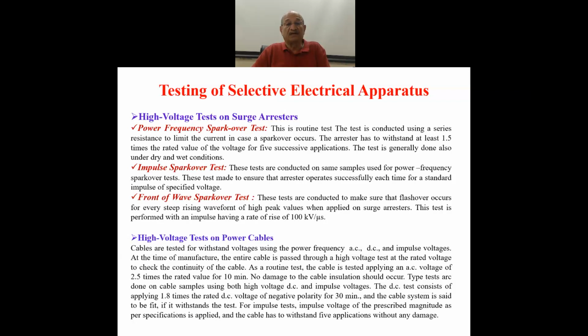Since there's a lot of insulation involved in power cables, it forms very high capacitance, and for that, the suitable equipment for testing high voltage power cables is the resonant test voltage generator. That means the inductance of the desired value can be taken into the circuitry, which takes place automatically.